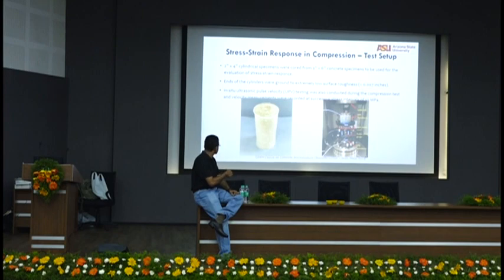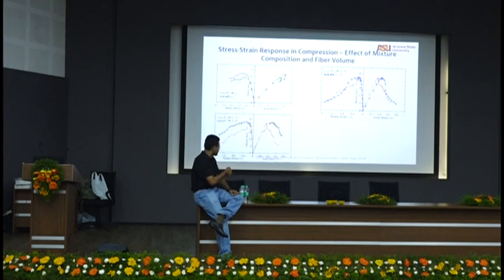Compressive stress-strain relationships, and I think I have them here. So here is stress versus axial strain and stress versus radial strain. So it is a triaxial test basically, not triaxial, uniaxial test, just with triaxial measurements. So you push it, your axial strain in this direction, your lateral or radial strain in this direction.